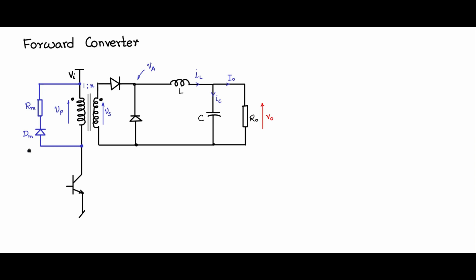On the primary side is nothing but a chopper or a switcher, and we will discuss the waveforms of the chopper and the switcher, and also this portion of the circuit where you are doing core resetting. These are the extra portions that will come apart from the regular buck converter waveforms. Now let us relate the regular buck converter waveforms to the forward converter.